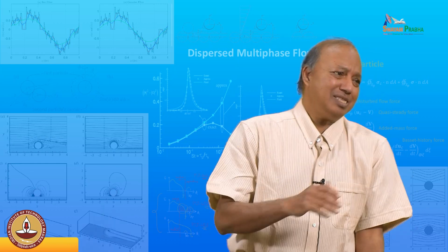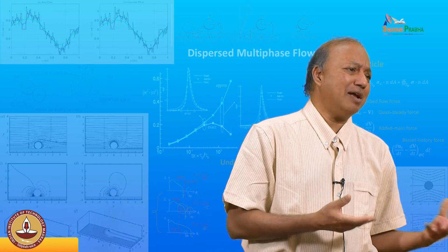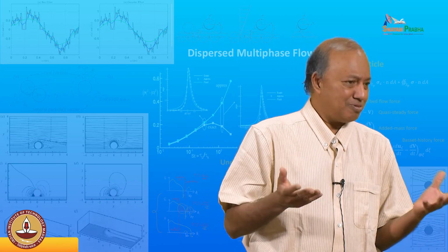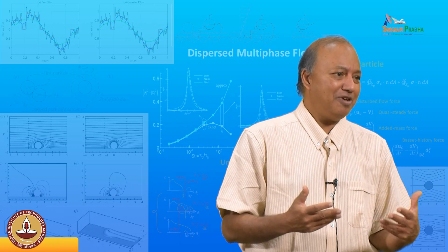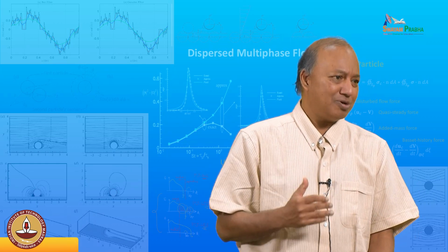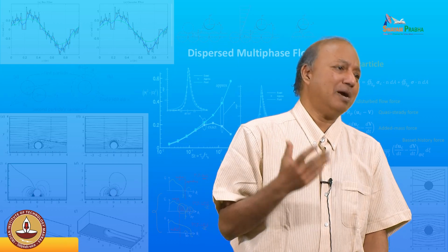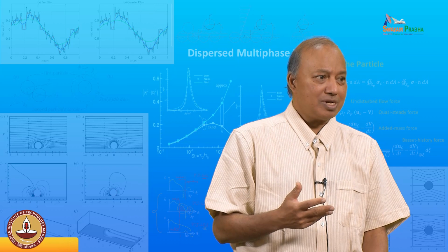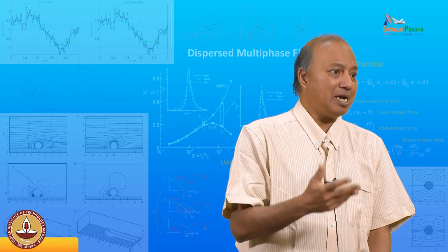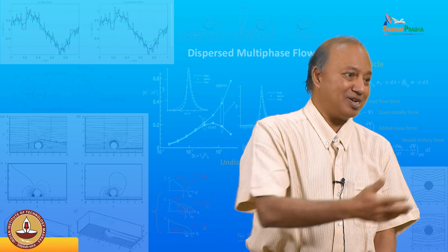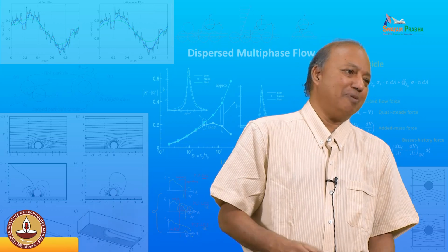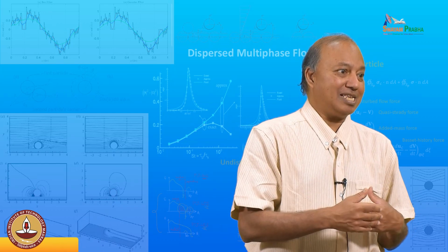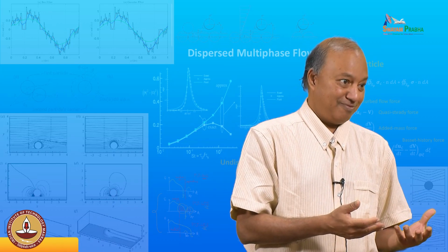Of course, you see, this is all loose talking. If that particle is just moving with the local fluid, then the force would be small. So the potential for a big feedback force, the main message that I want to give is, the bigger the particle, the feedback force could be large, and that feedback force could be a big component compared to your advection, etc. So you can't argue, oh, feedback force is small. Okay. So the next time step velocity may depend on that feedback force.